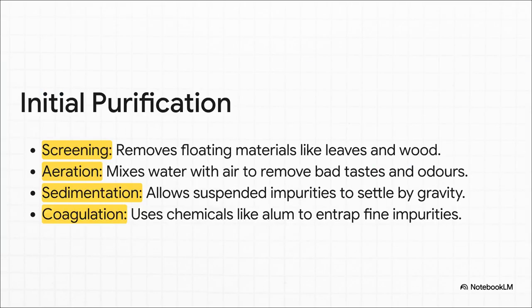The first few steps are all about getting rid of the obvious physical stuff. Screening is just what it sounds like, running the water through screens to catch leaves, sticks, whatever. Then aeration mixes the water with air to get rid of nasty tastes and smells. Sedimentation lets heavy stuff like sand just sink to the bottom naturally. But what about the tiny, fine particles? For that, we use coagulation.